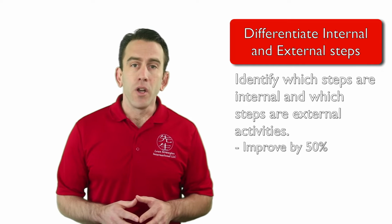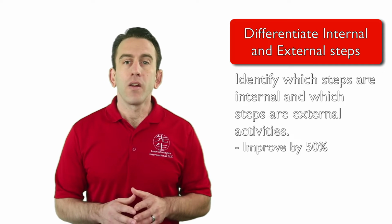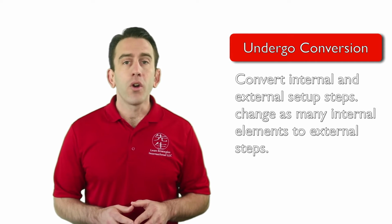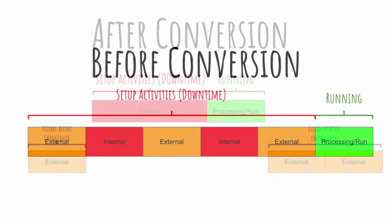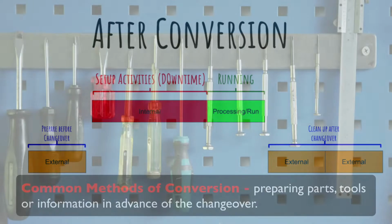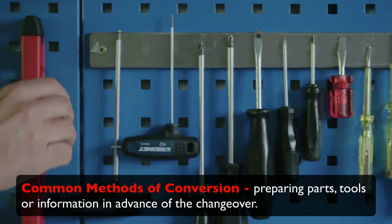This portion of the reduce methodology could result in as much as 50% reduction in your setup. After differentiating steps, we move on to undergo conversion. Now we are ready to convert internal and external setup steps. The objective here is to change as many internal elements to external steps. Some common improvements for conversion are preparing parts, tools, or information in advance of your changeover.